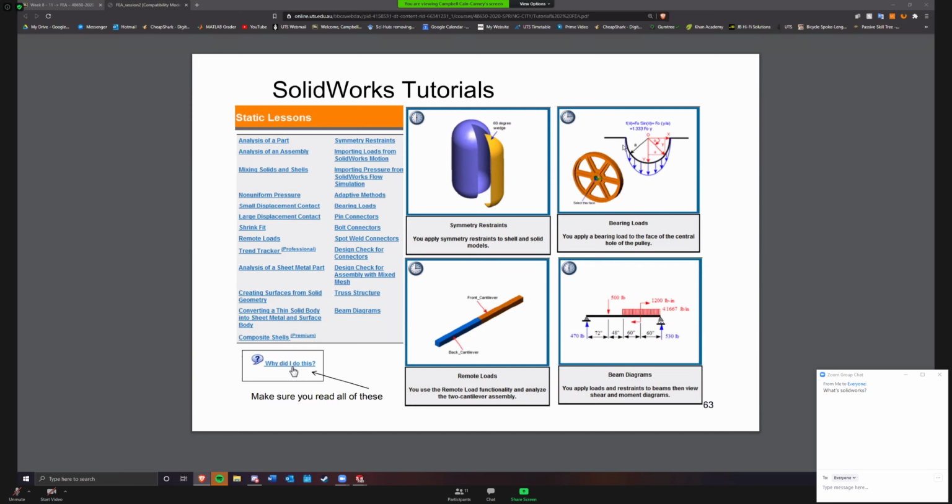But if you're pushing down on this hole with an evenly distributed force, you'd have a nice square edge here, then you'd have a nice even distribution across the whole thing, which in reality is not how a bearing load works. Now, a bearing load can be something from, say, just a shaft or a bushing. It doesn't have to be a bearing specifically, but this sinusoidal distribution will provide you with a different stress response in the material. So it's very important to understand how these actually work.